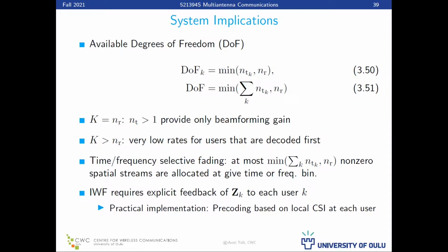Or it could assume a certain code book. It just decomposes KX and then finds an index in the code book which is closest, and then just feeds back the index that, okay, use this precoder from this code book with this index. Okay, but then of course it's not exactly optimal because there's some rounding, right? Because you would need an infinite code book to cover all the possible solutions.